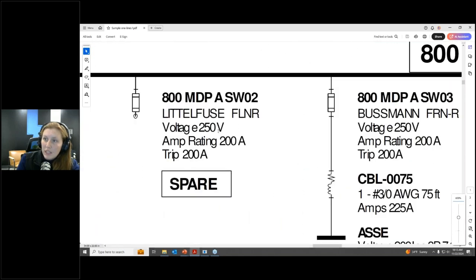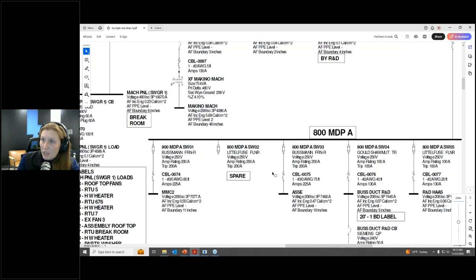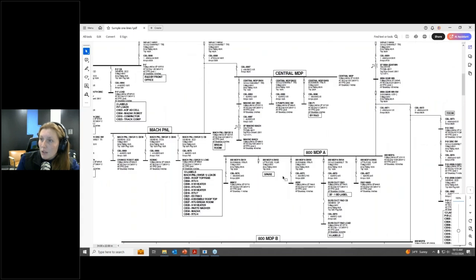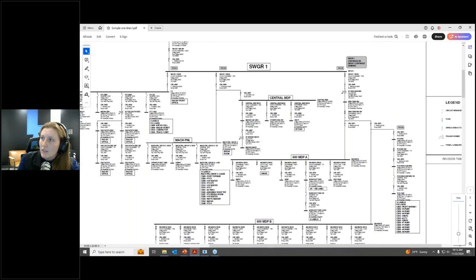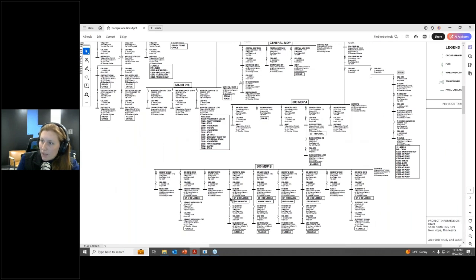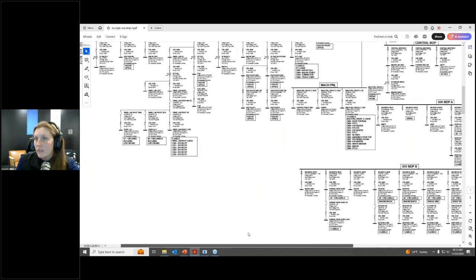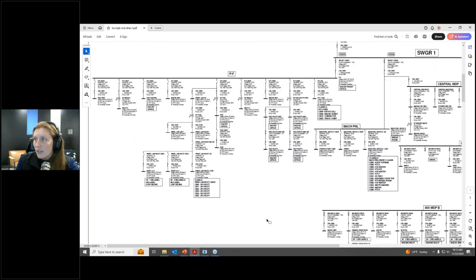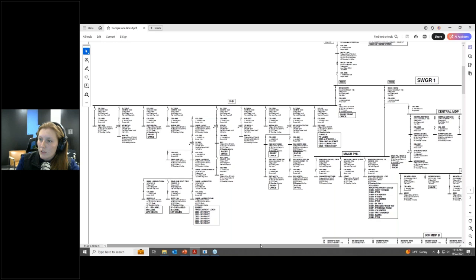Sometimes we even just see there's a fuse and it's got a note that says spare. There's nothing connected to it yet. That's pretty common. Or breakers that are put in place but nothing's landed on it yet. Go ahead and model it and then just list it as spare so that people know, yes, okay, that doesn't actually feed anything yet. It's free to use if the case arises. Okay. Let's see if there's anything else relevant for the data. I think we covered it. Fuses, transformers.